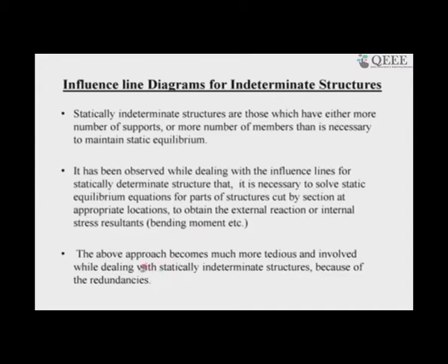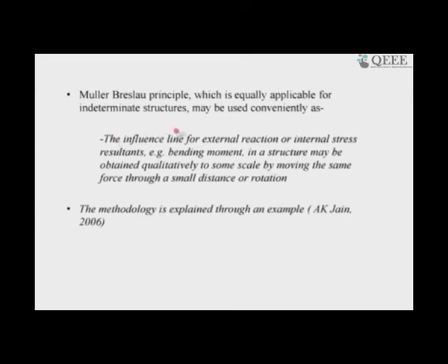Now, the above approach, which was very easy for statically determinate structures, will become much more tedious and involved while dealing with statically indeterminate structures because of the redundancies. So, if there is a redundant, finding out the deflections and others will be a challenging task. And so, the Muller-Breslau principle, which is equally applicable for indeterminate structures, may be used conveniently.